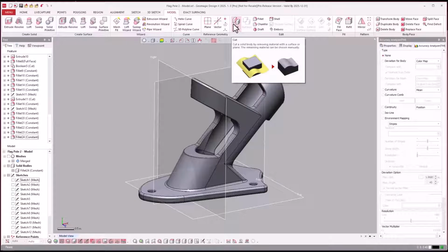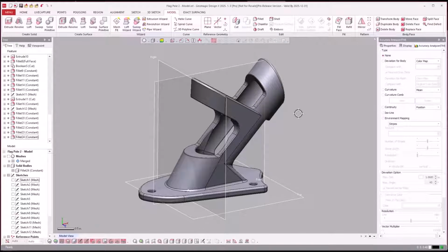We can actually select multiple surfaces and cut with them all at once, where SolidWorks doesn't let you. They only let you cut with one surface at a time. So keep that in mind when you're setting up your modeling. If you are a SolidWorks modeler, you're pretty familiar with a lot of those things that are particular to SolidWorks, so you model with SolidWorks in mind if you're going to model in here. And we try to model in a more universal way.